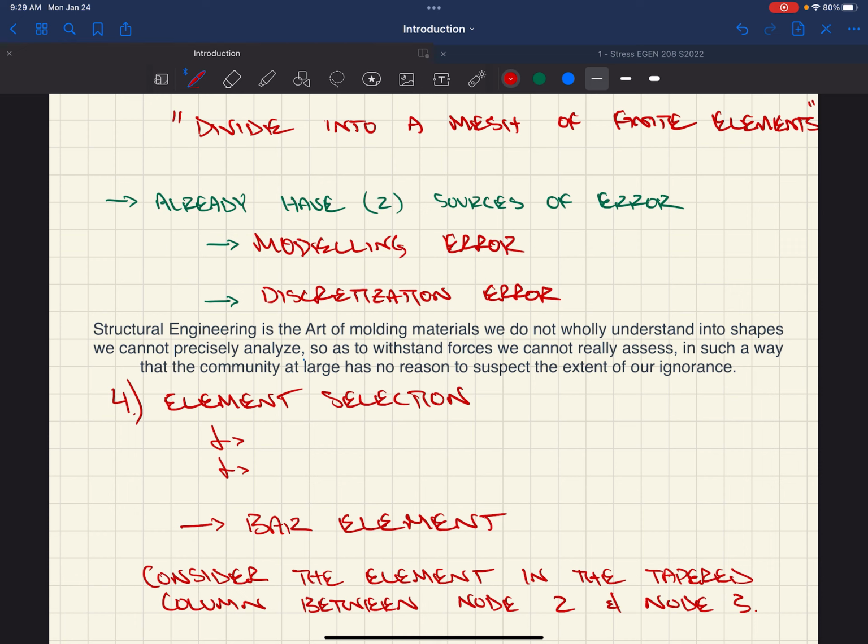So there's error in everything that we do because we cannot model the real world, right? Based on not truly understanding what the materials are. That column out there, we might think is tube 46 KSI, right? But in reality, it might be 52 KSI. We made all these assumptions based on what that is. We get into seismic design, overstrength, right? The fact that the material is stronger than it is a negative on us, right?